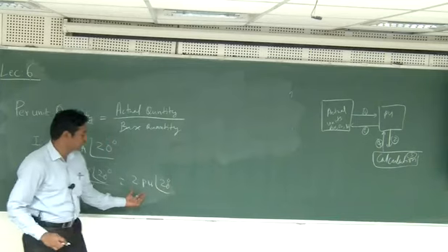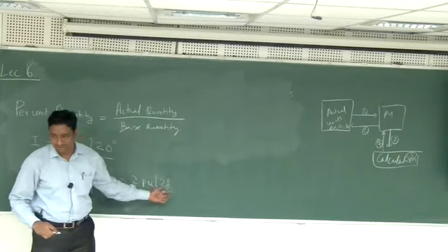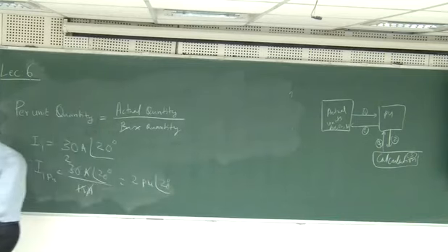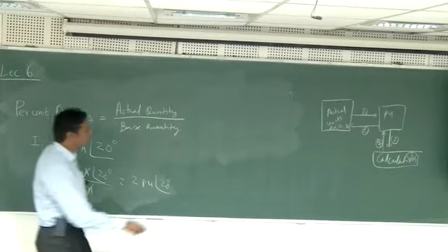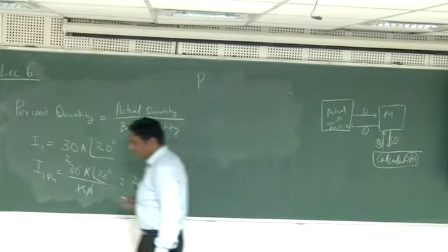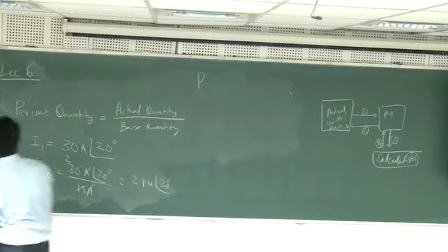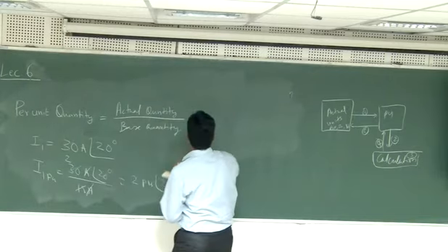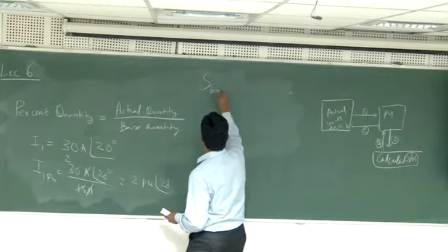I can always write 2 cos 20 plus j 2 sin 20, but that is also in per units. Okay. So this thing you should again notice. This is actually quite useful for the power. Suppose I have, let's say, MVA base or kVA base or volt-ampere base, something like that, S base.